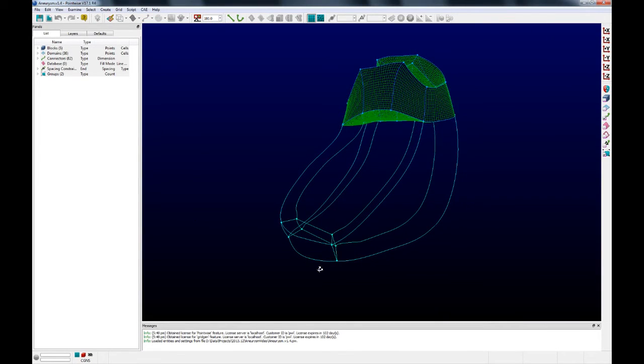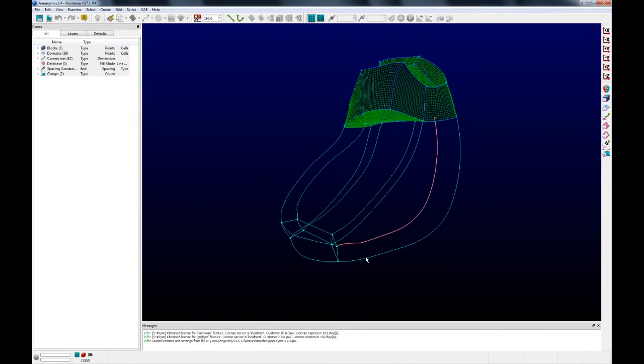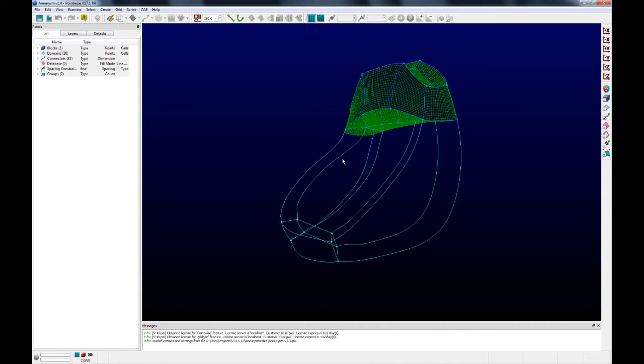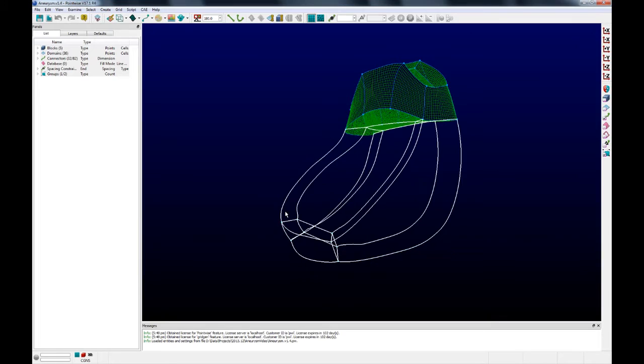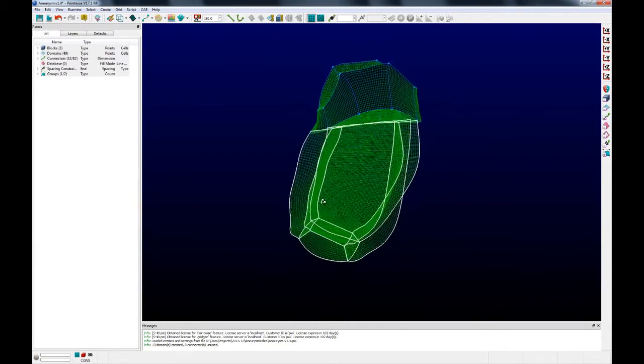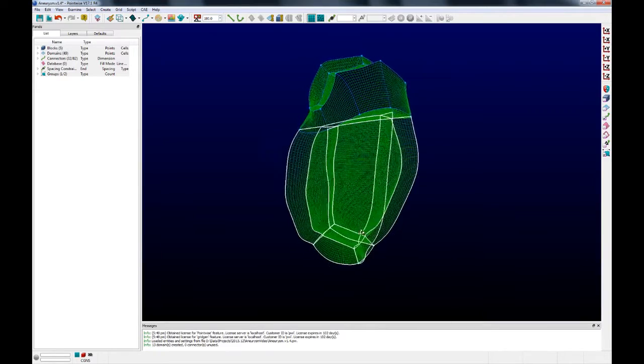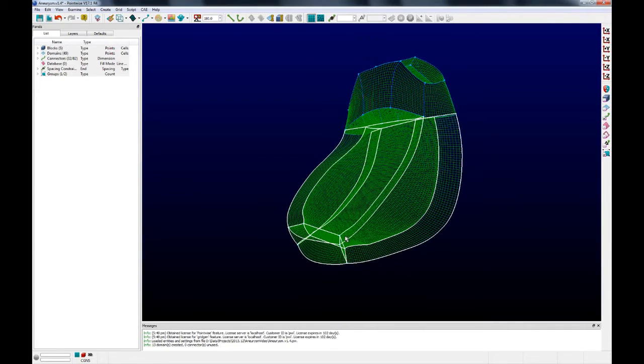And so now this has all of the internal structure, and all that's really lacking is the internal domains and everything. So I'm going to go ahead and select those. Again, I've grouped the connectors for convenience. We'll go up here, go Assemble Domains, and you can see that the topology is going to be created. So we have a nice internal structure ready to go.